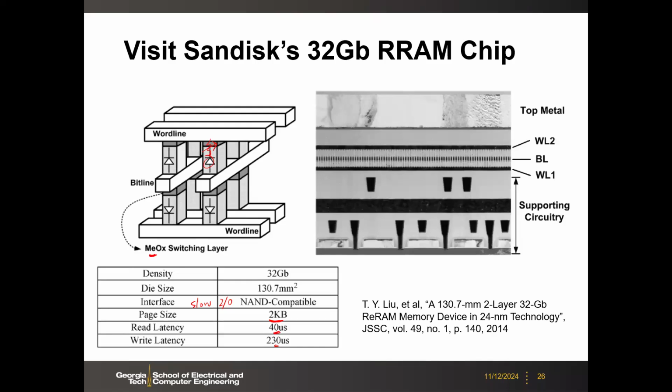So anyway, you see that this is a two-layer RRAM cross point integrated on top of the interconnect. Here the pitch is pretty small. I remember it says 24 nanometer. So the half pitch, this is F in here. This F is really 24 nanometer. Okay. It's half pitch because pitch is from here to here, and then the wire is half of that. 24 nanometer is pretty small, so that's why in this cross-sectional TEM image you see that this is very small.